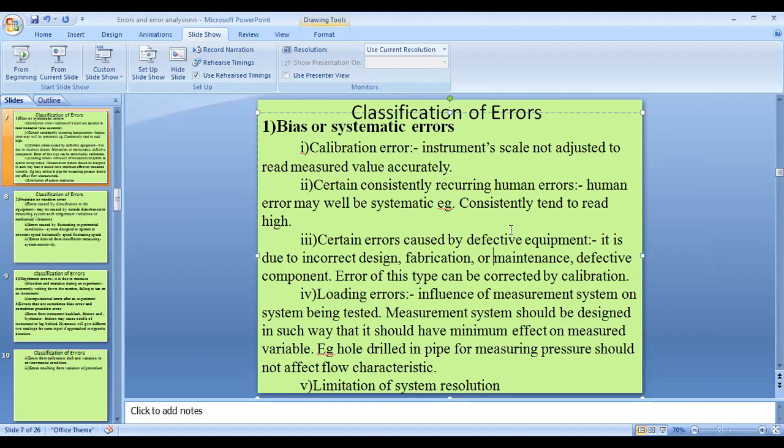So what precaution do we need to take when we load the system for measurement? You can take the case of an ammeter. What is happening in the ammeter? The ammeter will have its own resistance, so it will affect the system. It will consume some power from the system. There will be I square R loss in the system. So this loading should not affect the measurement accuracy. It should not cause error.